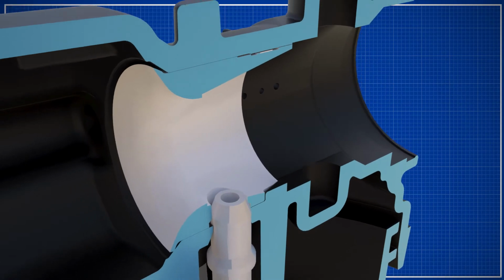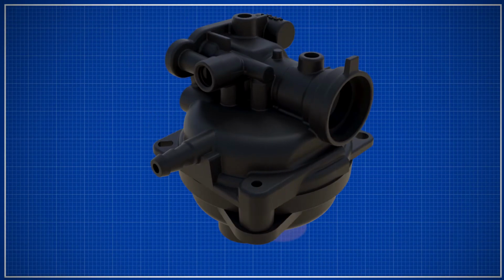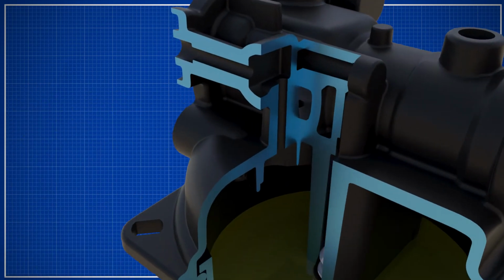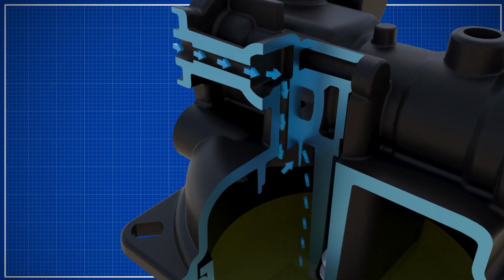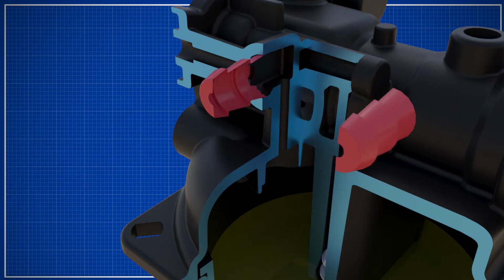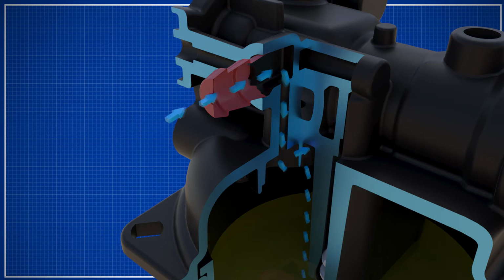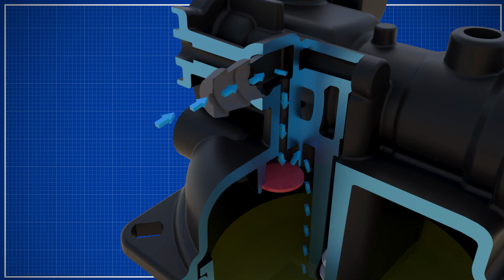The next feature added is the atmospheric bowl vent. The bowl vent is found in the front area of the carburetor when internally vented. Externally vented carburetors have bowl vents near the mounting flange. The bowl vent is a pathway. It lets atmospheric pressure go into the bowl area and be applied to the fuel. These vents are often baffled so that the fuel will not cause a blockage of the vent. Without a bowl vent, fuel is supplied to the engine for a very short time.